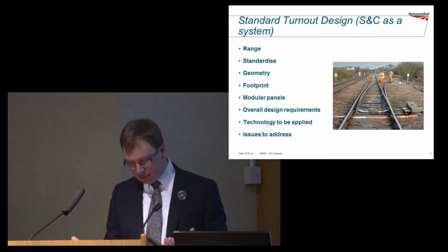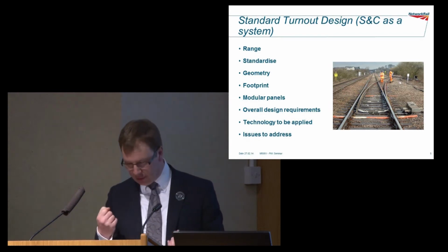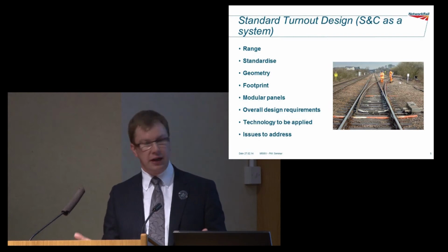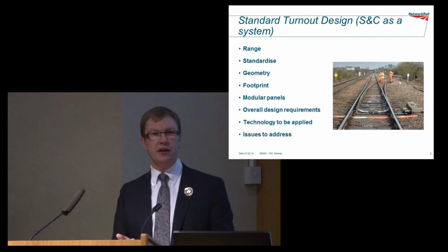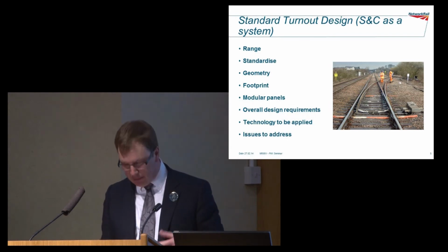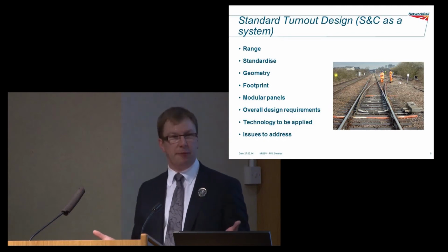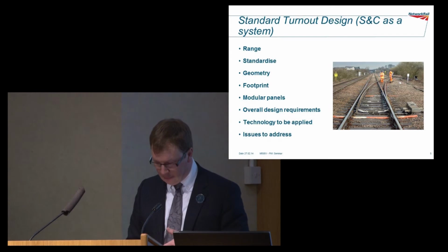So things like, probably more applicable to switches, but are we talking about shallow depth? Are we looking at fully welded turnouts? Are we looking to stress it? Are we going to use direct fixed bearers or base-plated bearers? Things like metric bolts, what type of clip, what type of pad. They're all things that we need to agree early on in the day.